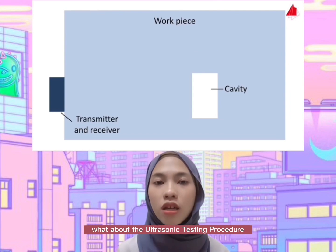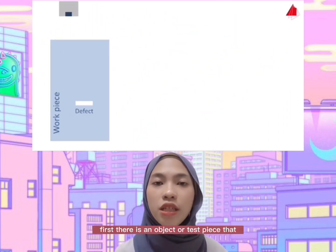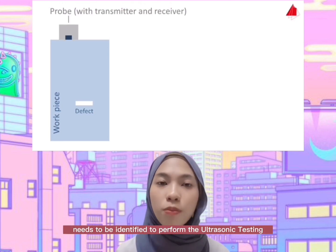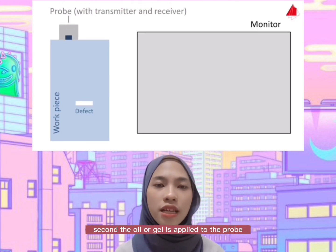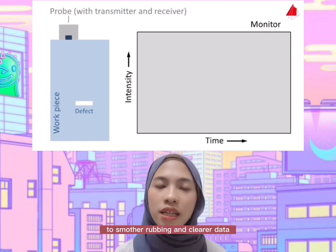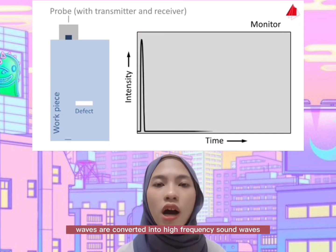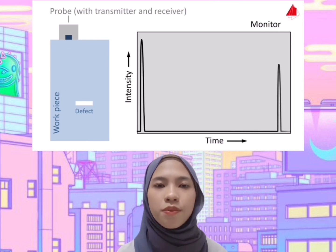Next, let's explain the ultrasonic testing procedure. The first step is that an object or test piece needs to be identified to perform the ultrasonic testing. Second, oil or gel is applied to the probe for smooth rubbing and clear data. The probe is placed on the object, where electrical waves are converted into high frequency sound waves.